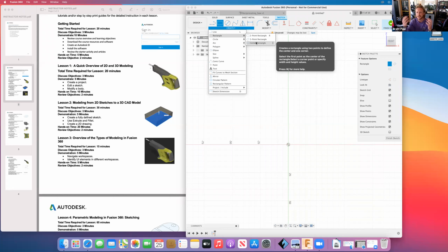So you created a simple sketch, you defined it, you finished it, and then you extruded it into a cube. From that, you picked a face to create a new sketch on, where you could then build that part into a more complex part. So you built a trough, or did an extrude cut step into the cube.